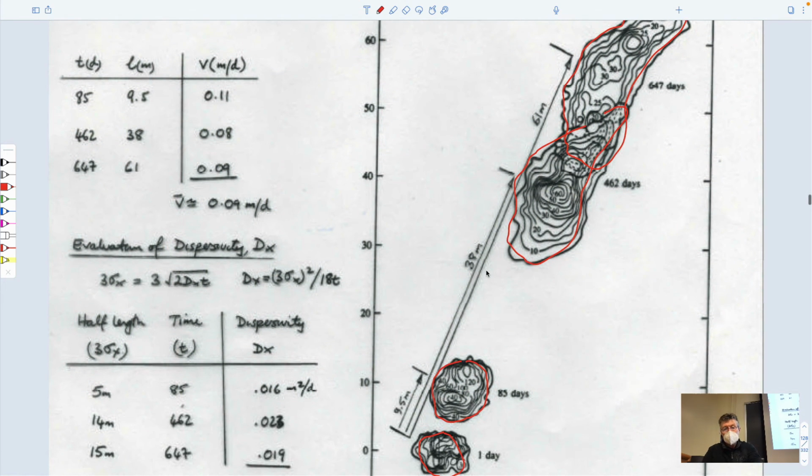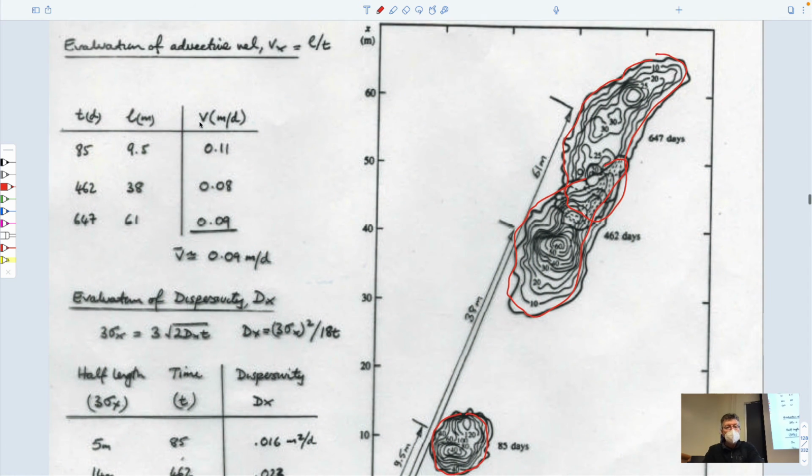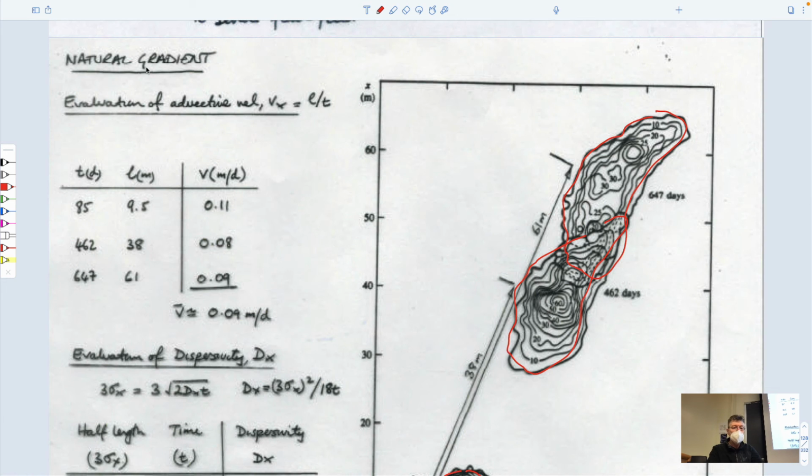And so it's certainly sampling a big part of the aquifer, 60 meters. It's certainly moving only at the velocity that the fluids are natively moving in the aquifer. And so it's moving under the natural hydraulic gradient. So the gradient refers to the hydraulic gradient that's driving flow. So in other words, advective velocity is equal to K over mu, 1 over porosity, dP/dx. And it's an unconfined aquifer, so really it's just the gradient of head within the aquifer.